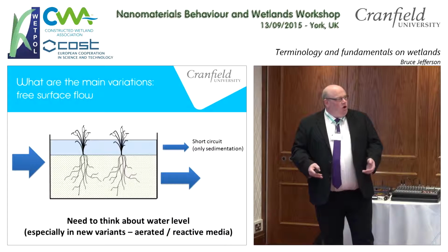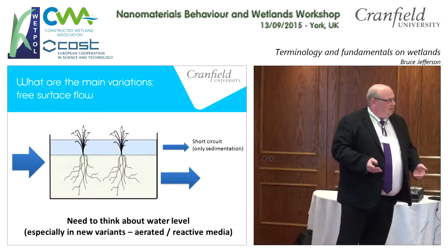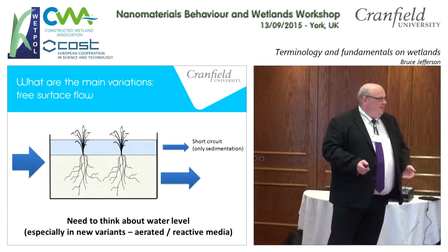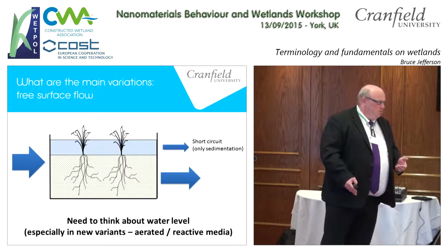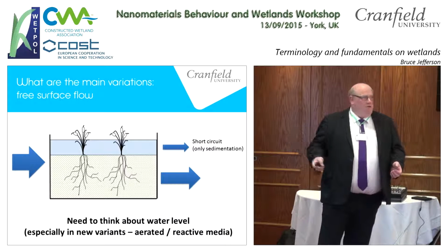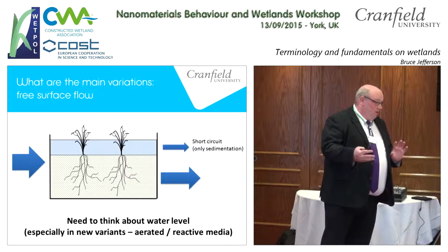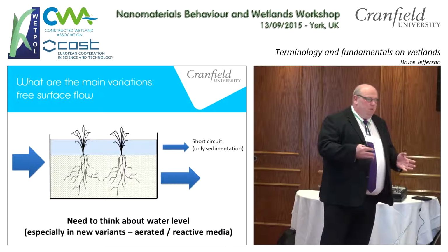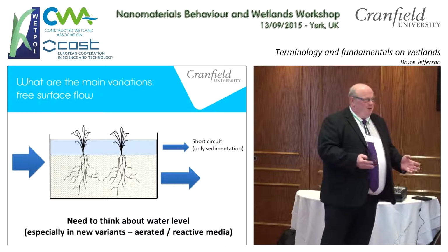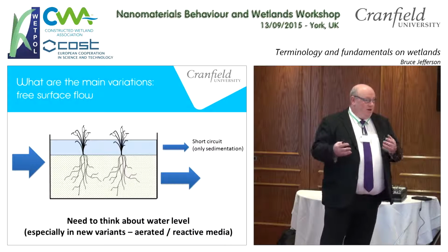So it's quite common, to help prevent operational problems around weeds growing and other things like that, to just run them a little bit above gravel level. No one pushes it down as they mature and it stays that way. That offers a big route for short-circuiting. In traditional wetlands, these horizontal subsurface flows that we use a lot in the UK, it's not such an issue. But if I'm now starting to talk about removal of colloidal nanoparticle associated material, well, they don't settle very quickly. So actually, they may pass through this short circuit route. So I need to think about it a bit more.